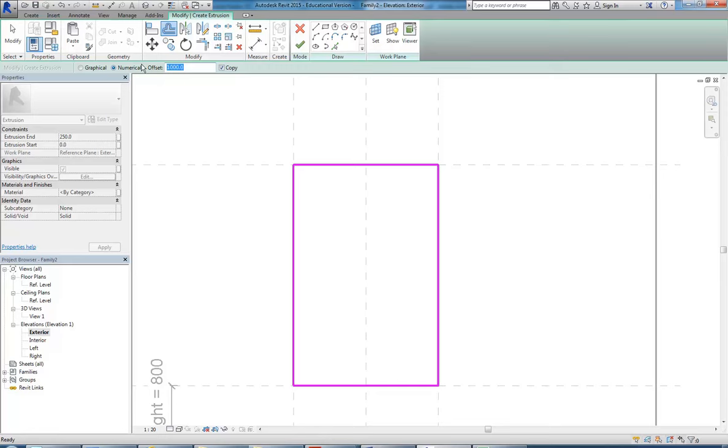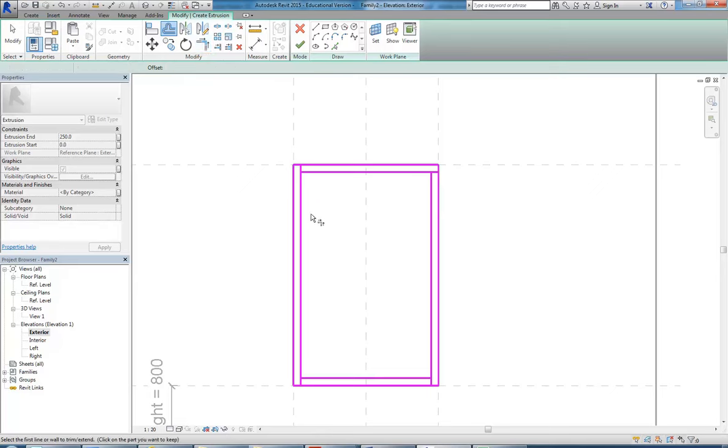And, well, do you know what the standard size for a window jamb is when you're just drawing a simplified one in plan? Yeah, look, if they're metal they could be, but for timber 50 is probably the standard. For doors, you draw them 40 mil, but then it's just a bit of a convention. You draw them 50, even though in reality, you probably know if you've ever built a window or done any building work, they're not that size at all. It's just a drawing convention. So I'm going to do it 50, and then pick each of these sides. If you want to, you can use tab to save time there, but if you pick them individually, you just need to go and trim them.